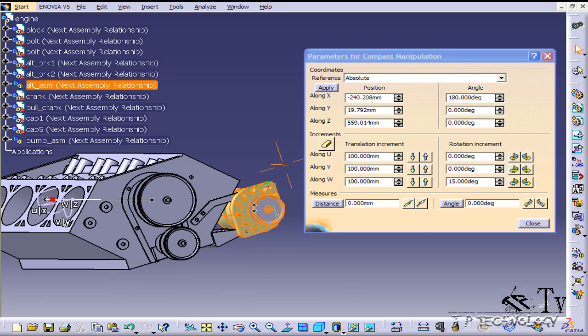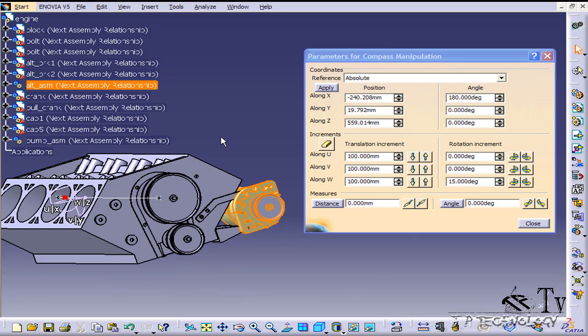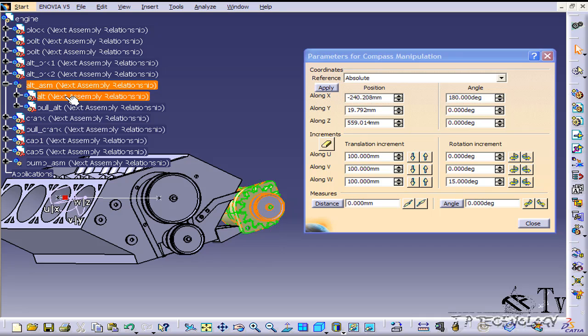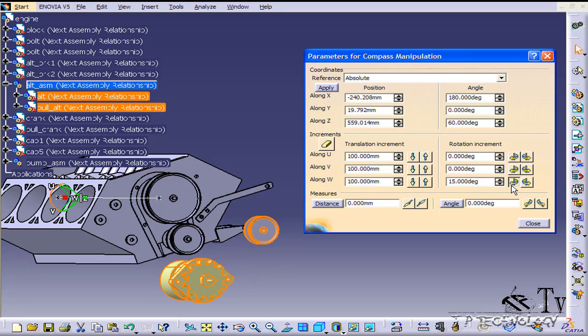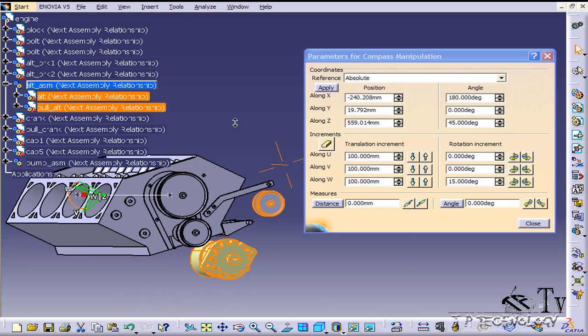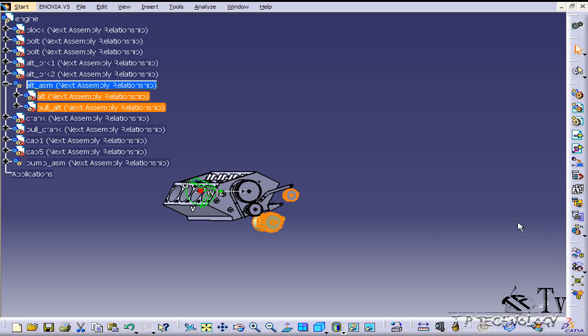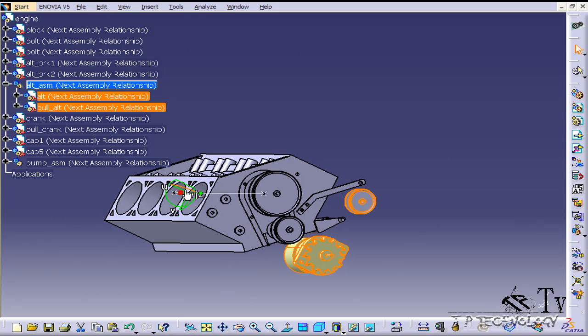the alternator here. And we're still going to use this as our axis point. Open it up, and let's just rotate this one guy. And you can see that only he is rotating. And as we select both, we're able to rotate both at the same time. So again, this works by using this axis that we've created. And this is going to create a consistent axis. So every time we go to rotate, it's always going to be the same result and the same rotation that you get.